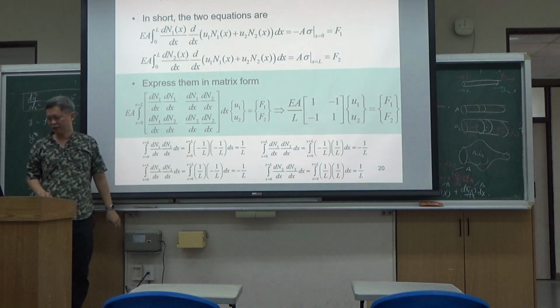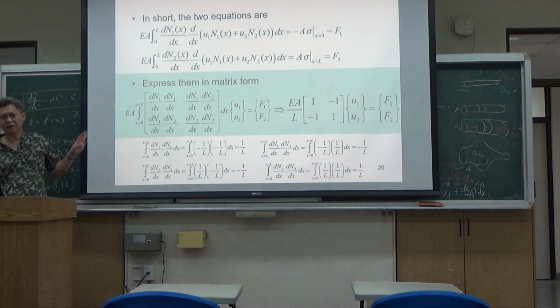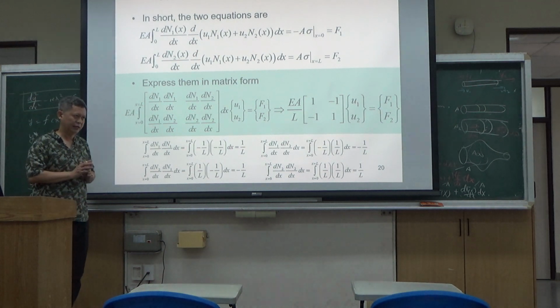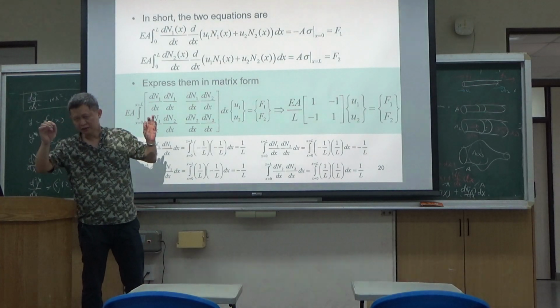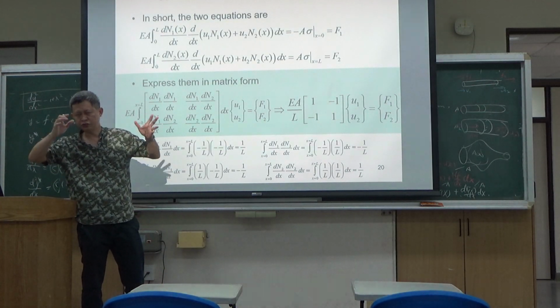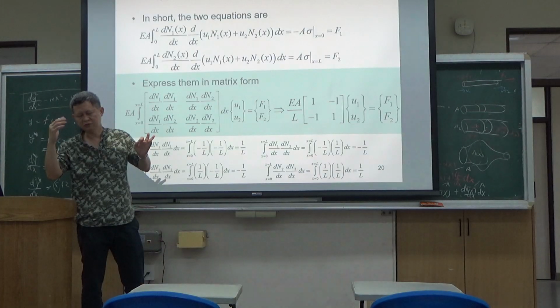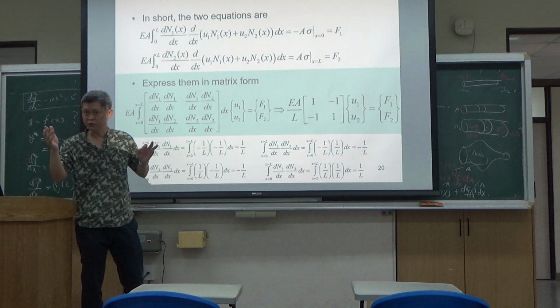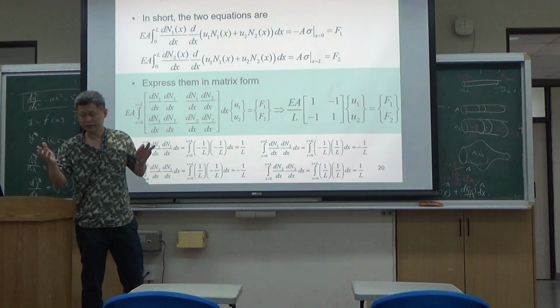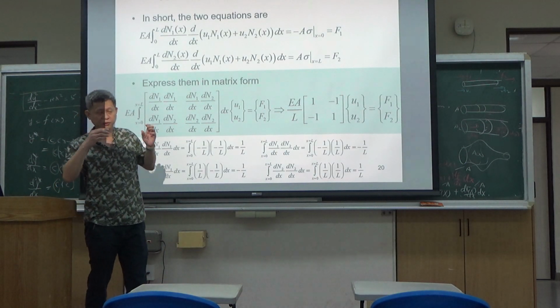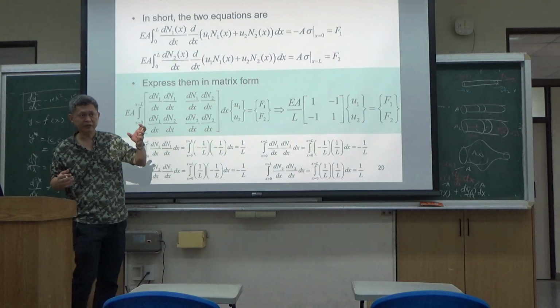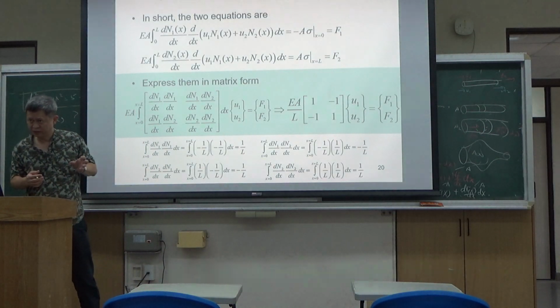Okay. So what is the purpose of this part? The purpose is to tell you that your rod can be a discrete one, described with Hooke's law, and you can find the truss equation using the assumption of discrete truss. But at the same time, if you treat it as a continuous rod, you can solve it using the energy method.